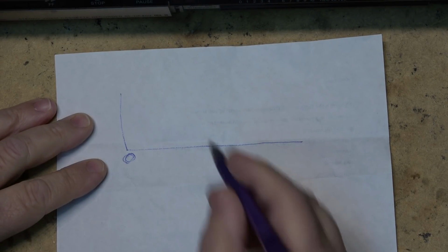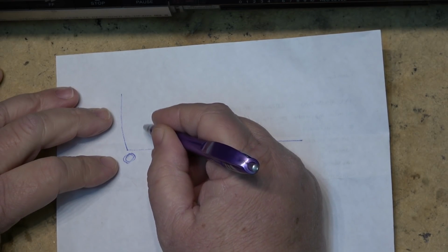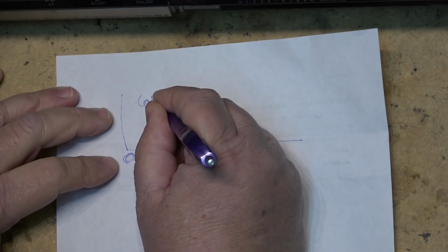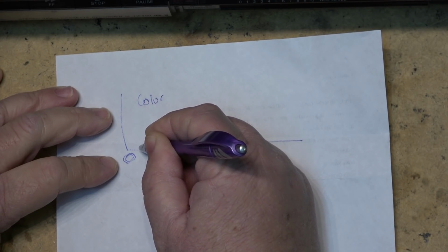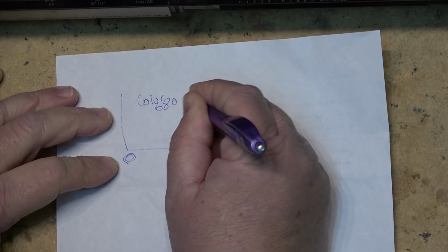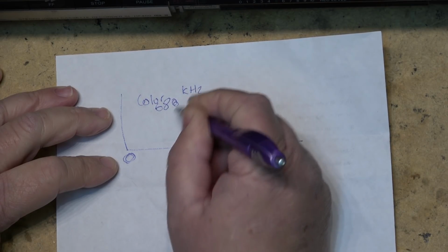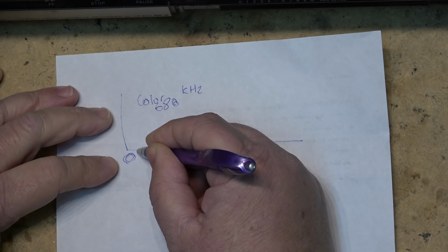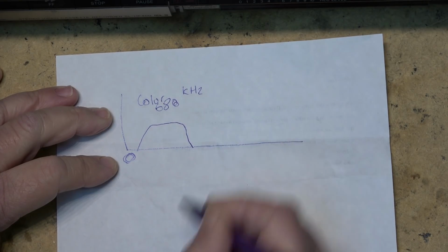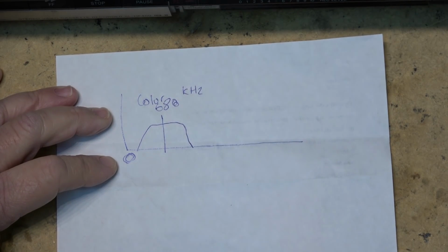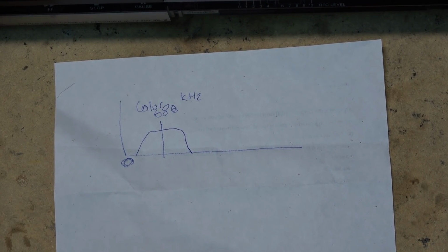So on Beta, you've got your color, which is recorded around 600, well actually it is recorded at 688 kilohertz. So your chroma is recorded in this frequency band, centered at 688 kilohertz. And one thing I'm not going to do is go into the exact frequencies, because I'm working off memory, this is something I learned almost 40 years ago, so I might be a little bit off on the frequencies. I'm not going to even go into the frequencies, because someone out there is going to troll me on the frequencies if I'm off.